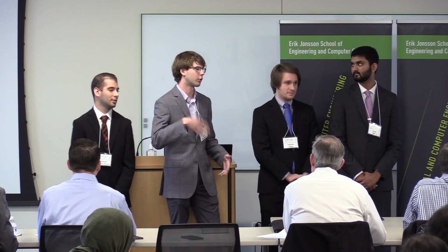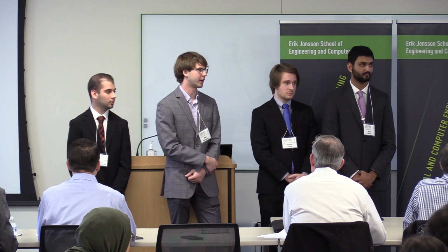Okay. What sort of capacitors were you using? We're using multi-layered ceramic capacitors. And what microfarads? I'm bound by NDA, so I can't reveal that information. Well, we can tell more, I think. We were using lower microfarad capacitors. 1 microfarad, 4.7. Yeah, just general microfarad. Not tantalums, though. That's the main thing. They have really high leakage.